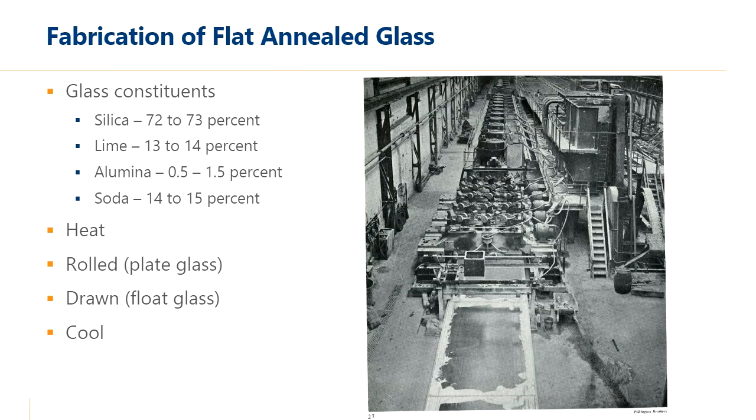While we're focused on modernist architecture for this presentation, the information on glass is applicable to other architectural styles as well. Glass during this time period often consisted of plate glass, a type of flat glass known for its smooth surface and clarity. The classic method of making plate glass involved heating raw materials and spreading the molten glass onto a flat surface to slowly cool, which relieves the internal stresses. This process is known as annealing. The glass was then rolled and polished to remove imperfections, which is shown in this photograph.